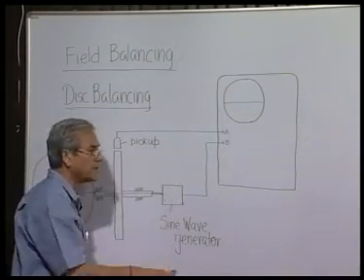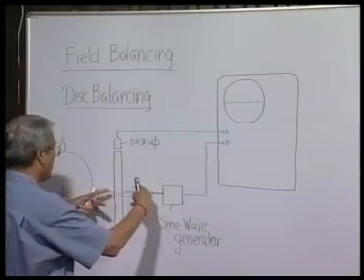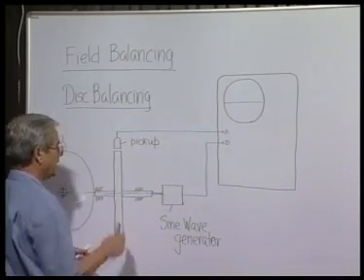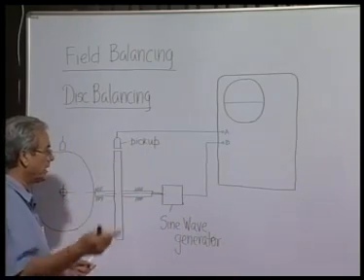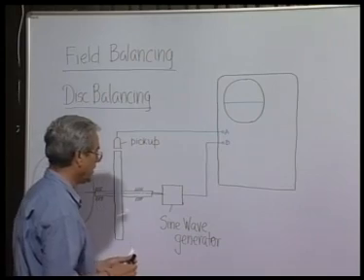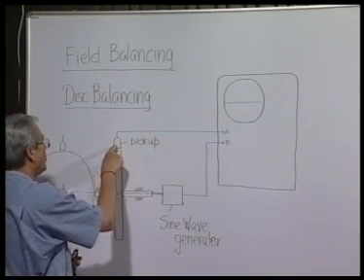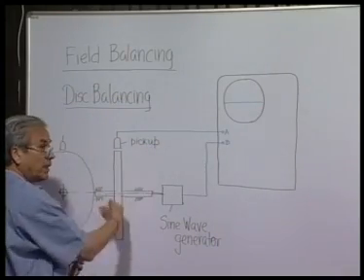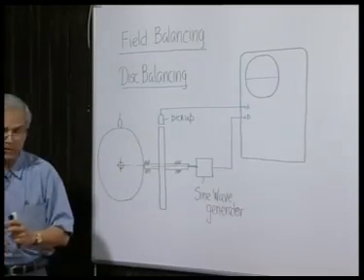This will produce a simple sine wave, and it is physically locked with the disc, because they are rigidly connected. So, the sine wave generated represents the rotation of the disc at its angular position, whereas the other will show the vibration of the disc because of the unbalance present, when it rotates at some suitably large speed.